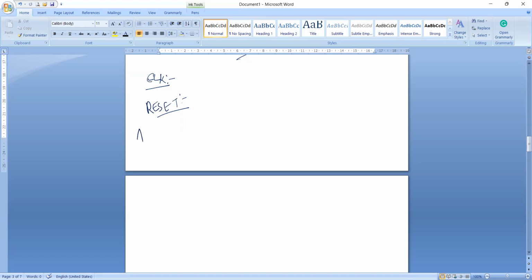And next, A0 to A3, these four least significant address lines. Under slave mode, these lines act as input signals, which select one of the registers to be read or written.